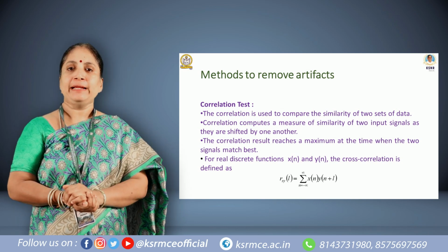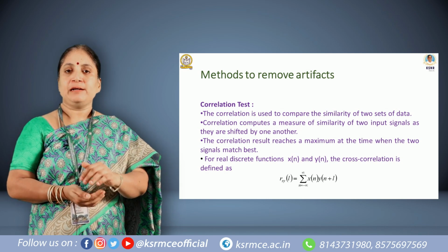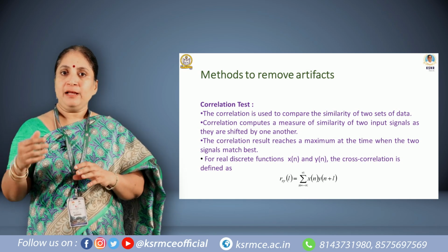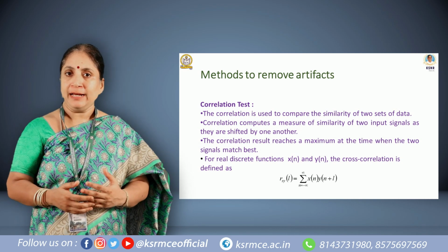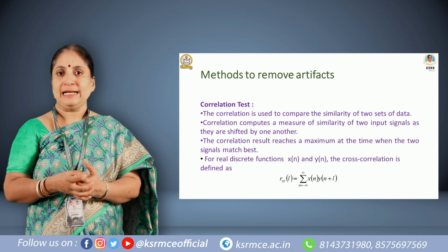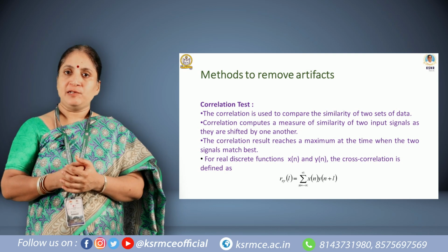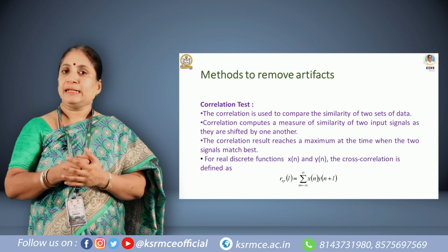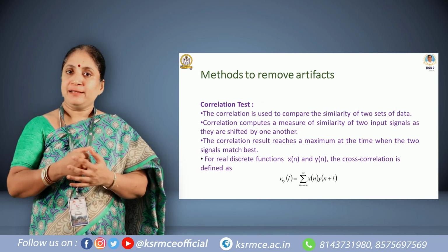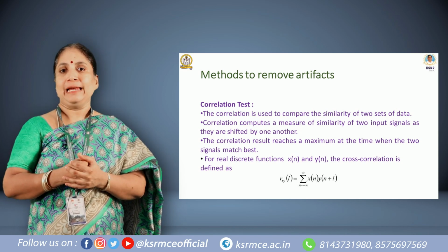Next, we are going to obtain the correlation coefficient of each individual signal as compared with this ensemble average. As the signals are very closely related, we are going to have a large correlation coefficient. If an artifact occurs in any particular case, that particular signal deviates more from the actual signal, which means the correlation coefficient will become less.